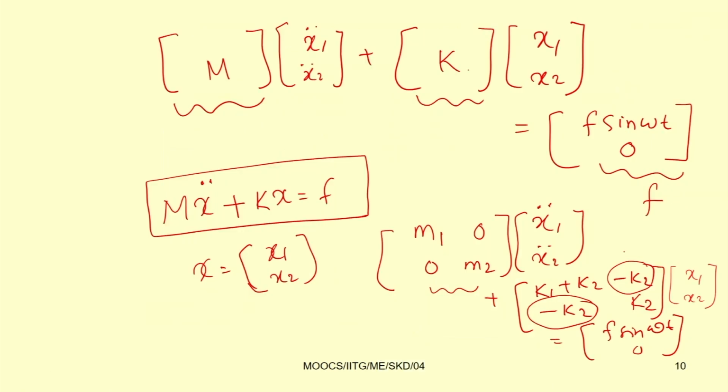In the linear case, the modal analysis method is used to uncouple this equation of motion. So, if it is linear, then we may apply the modal analysis method. So, what is modal analysis method? We can write this equation, for example, m x double dot plus k x equal to 0, taking the case of free vibration. If it is forced vibration, then it will be f.